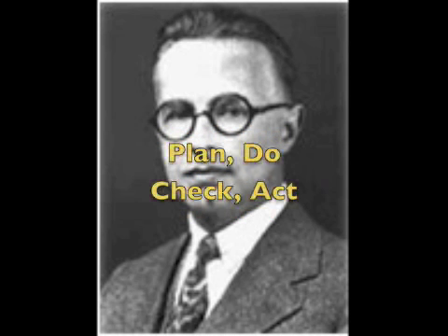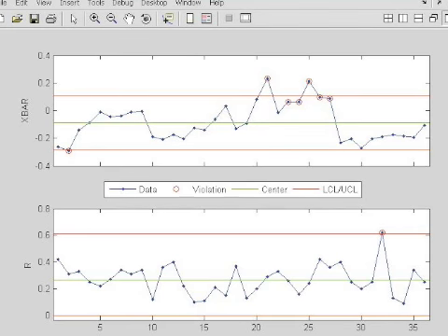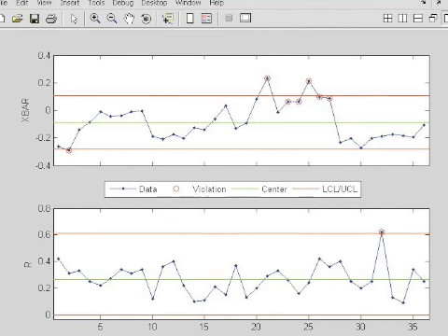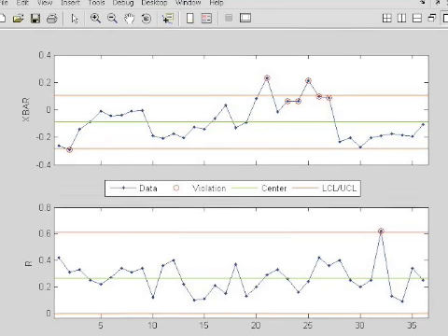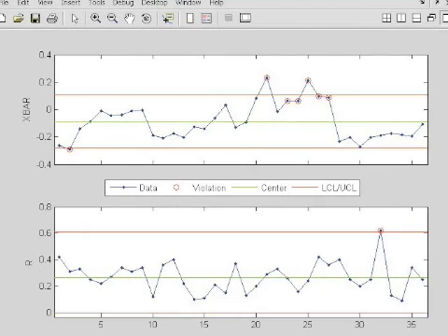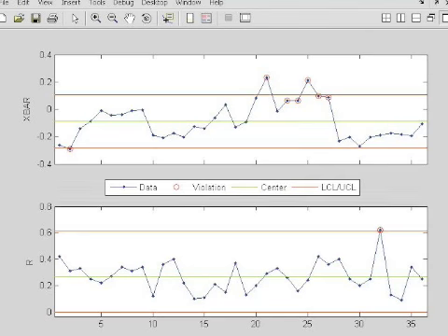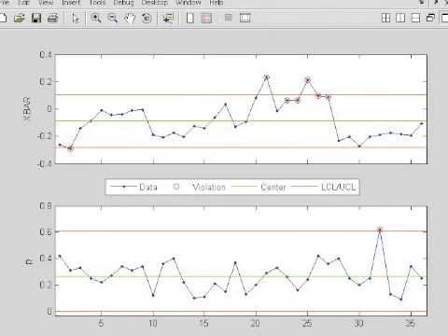Statistical process control, or SPC, is a way of managing the variance of a process using probabilistic techniques. It identifies problems as measurements that fall outside of a statistical limit that's based on historical and current observations. It defines the events that fall outside of these limits as due to one of two causes.